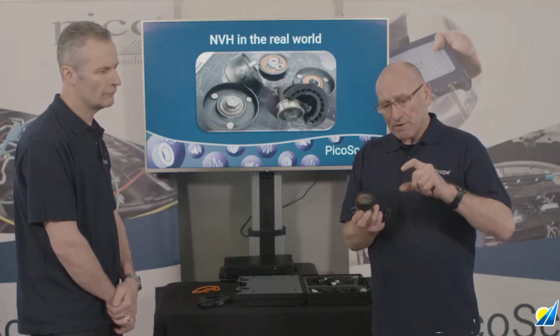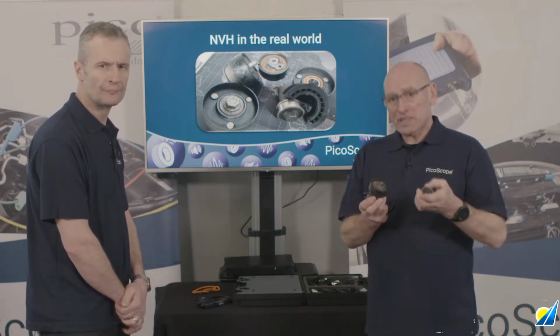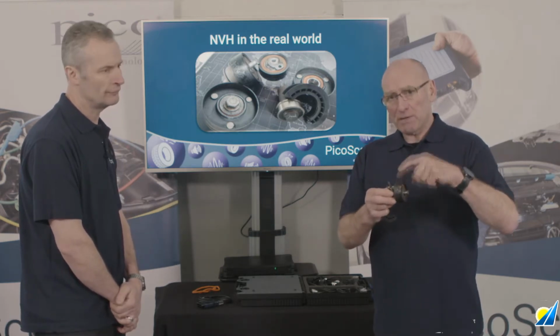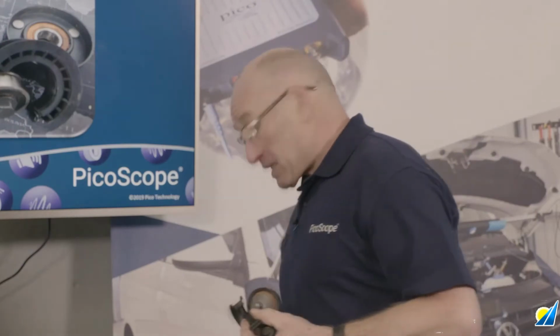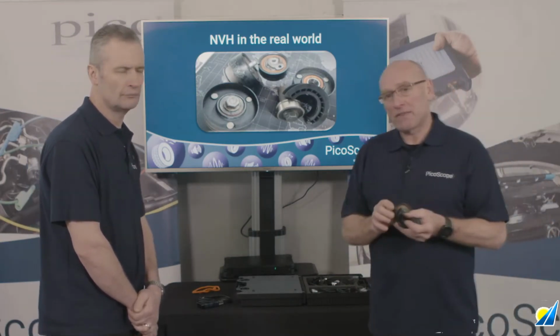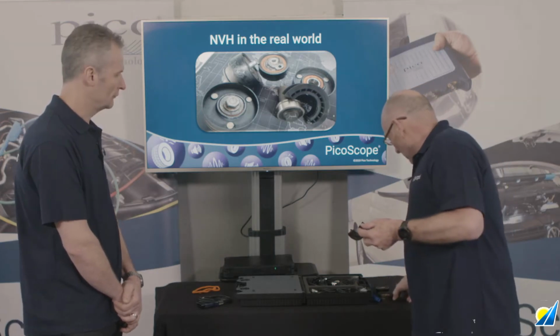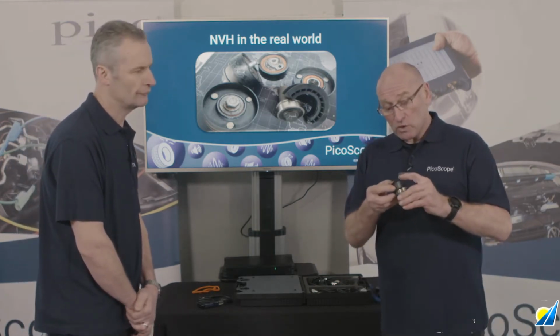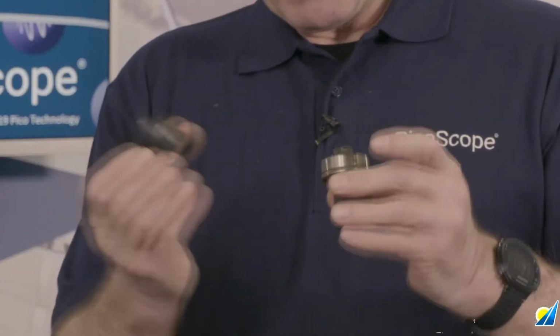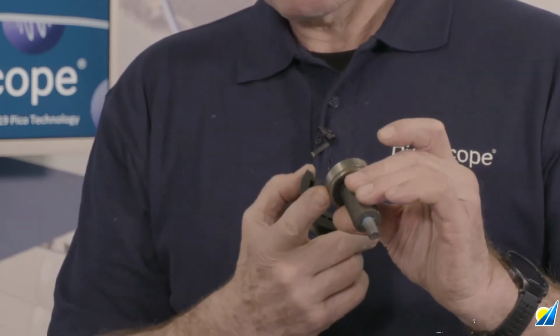So why is it that this vibration, this E2 event, appeared to be more prevalent at a certain speed? I put that down to resonance, where perhaps the effects of the belt depositing on this pulley, coupled with the effects of the bearing that was in the process of failing with this pulley, those two forces add together and produce this peak. The other very interesting thing about this is how did these two events then relate to a DTC for EGR flow? Well, that comes down to this part of the problem. The timing belt would normally run on that radius. The belt now is running on this radius, therefore the valve timing relative to piston crown position was now in error. This is the clever bit.